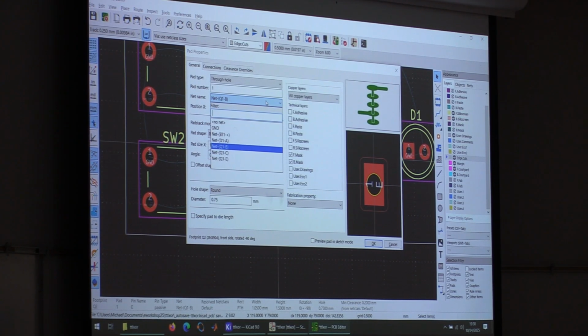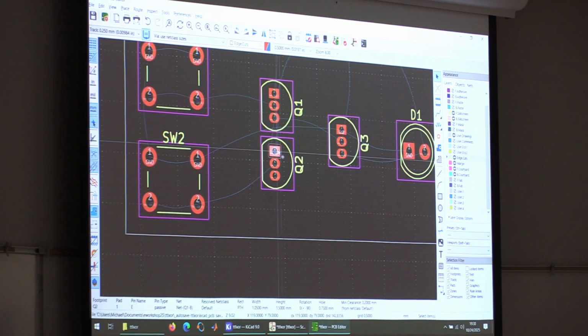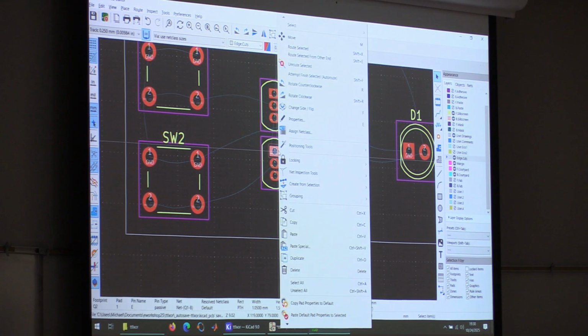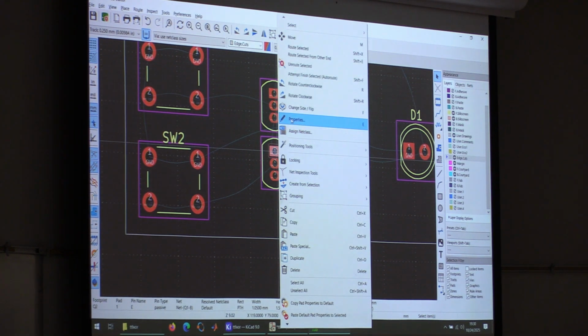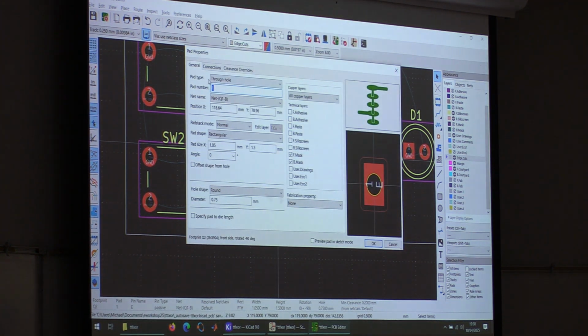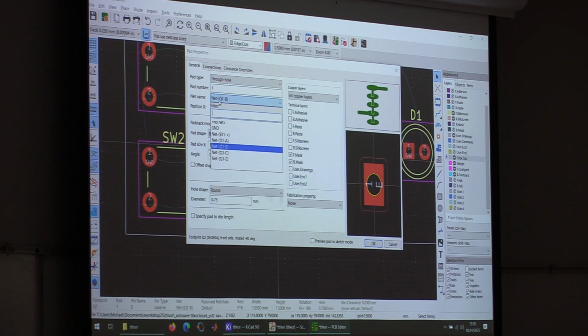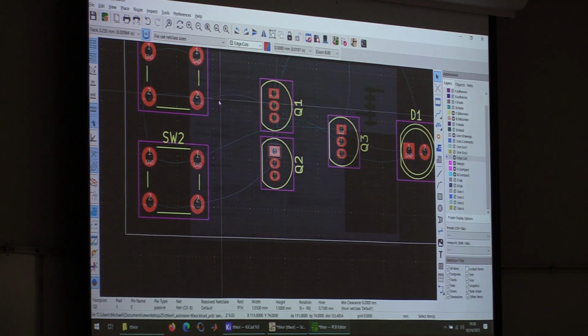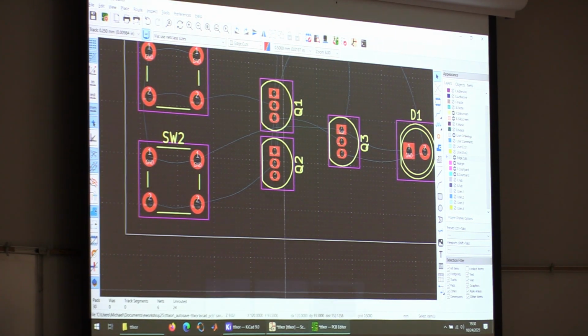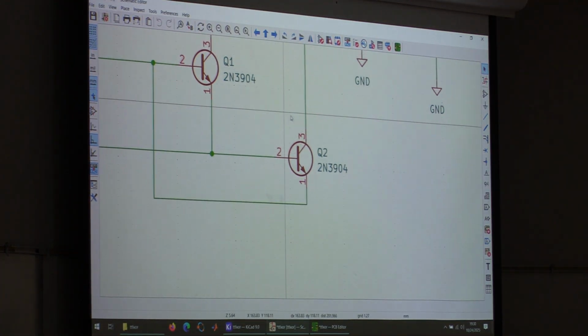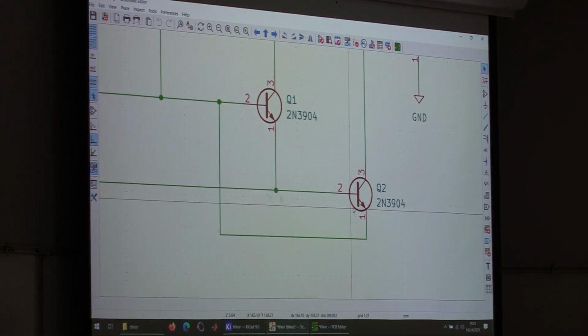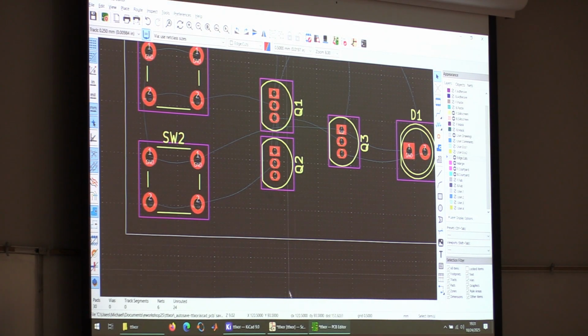It's not opening the properties of Q2? Yeah, if you go to just the pad itself. Okay, and then connections? No, it's just the net name. It says unconnected. Okay. So if you go to your schematic with Q2, that is the square pin, which is pin 1.